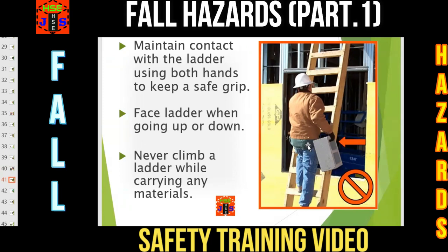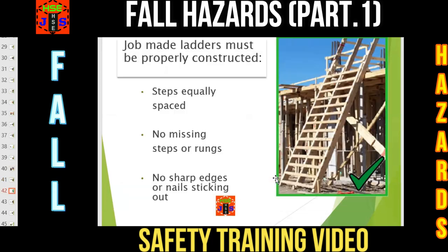This is totally not acceptable because at a time you have to maintain 3 points of contact. This kind of attitude, this kind of work practice is not allowed, not acceptable, and it may lead to a workplace accident. Remember, job-made ladders must be properly constructed.